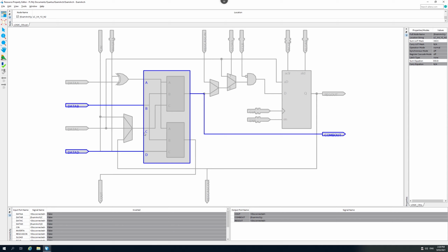In this particular case here, we see how it's configured, this logic element. Each logic element is highly configurable. These are FPGAs because you configure them. And in particular, we can choose for each logic element whether we're going to use the lookup table, or whether we're going to use the flip-flop, or even whether we're going to use both together. So the blue lines show what it's chosen to configure this particular logic element to be.